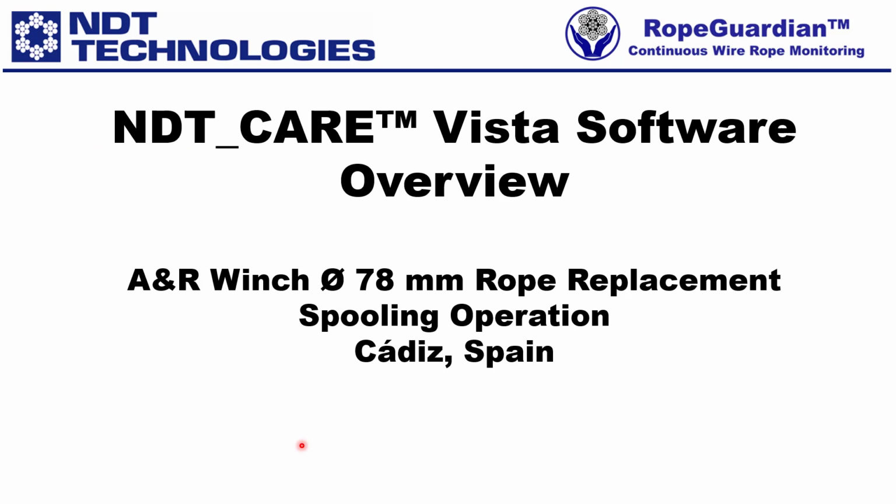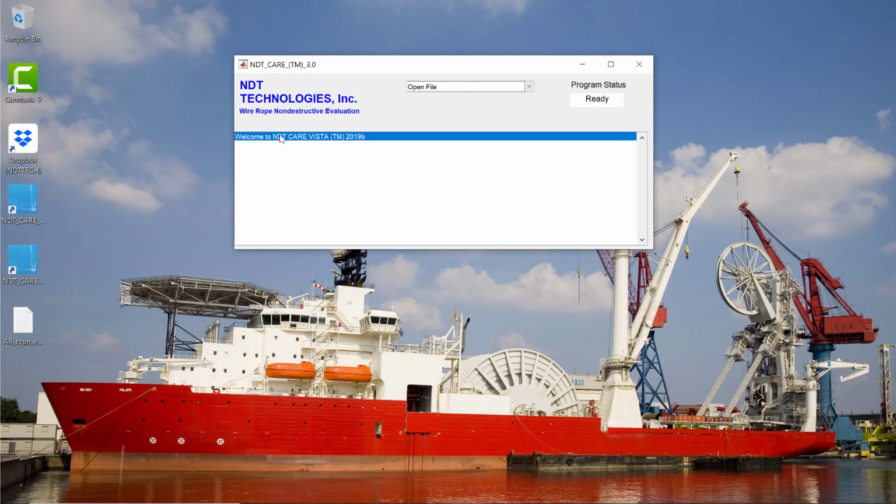Upon completion of the MRT inspection, software such as our NDT Care Vista software can be used to display the data and to perform a complete analysis, which can then later be used for report writing and trending analysis. Our computer-aided rope evaluation, in short, CARE, software is used for analysis. For this particular application, we'll investigate an A&R winch rope with a 78mm diameter that was part of a spooling operation in Spain. Okay, we have opened our NDT CARE Vista software.